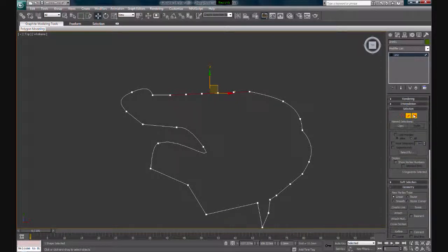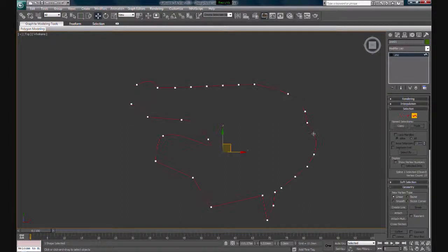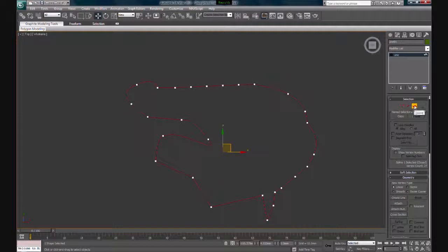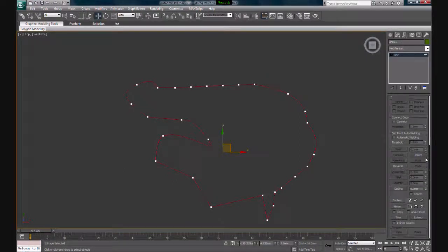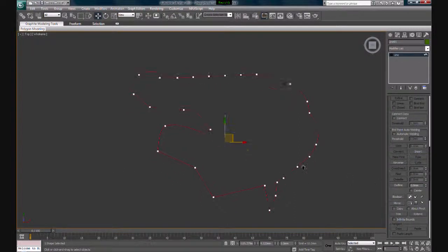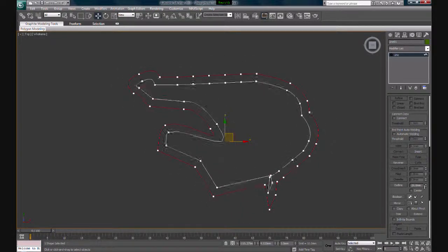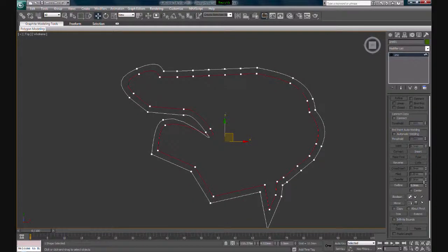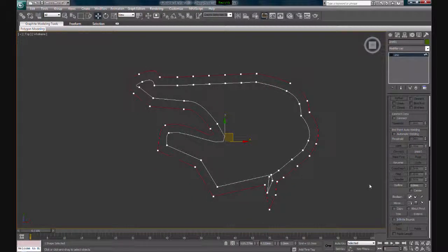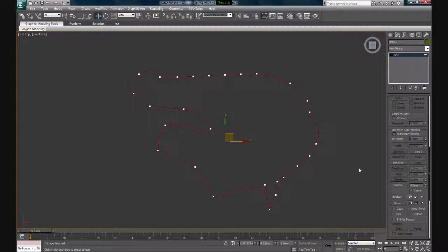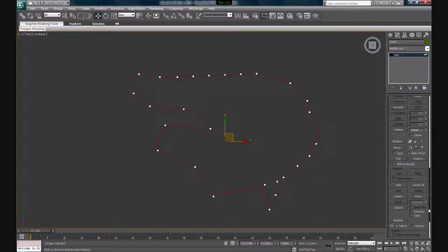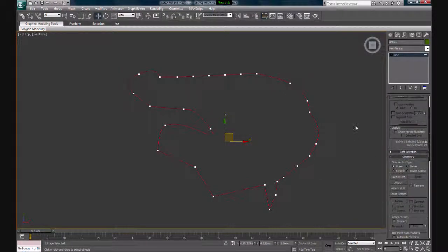If you go to Spline, basically it selects the whole thing. And the interesting part about spline modification is you can actually put an outline. Outline is almost the same as offset in AutoCAD. See, you can go inside or outside depending on the number. Negative goes inside, positive goes outside. So let's undo that. You can take your time to explore around.